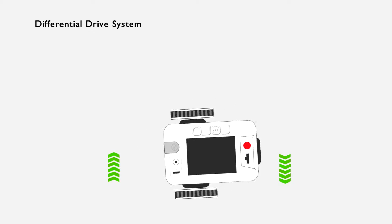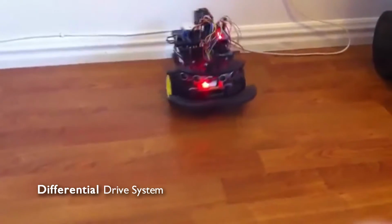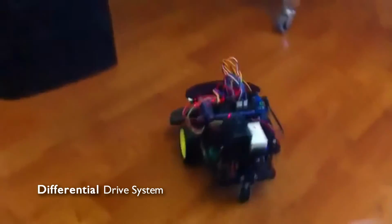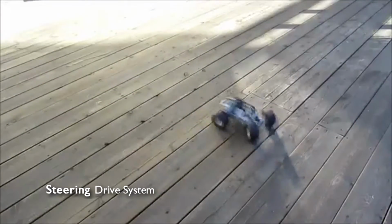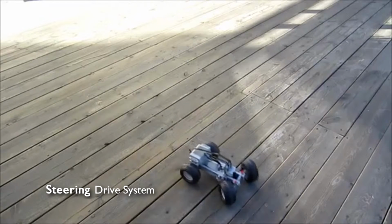at the same speed. Although differential drive system enables a robot to move around flexibly, it needs 2 powertrains or 2 motors to deliver torque to 2 independent drive wheels. It is impractical for vehicles on the road to have 2 engines due to the cost and complexity. Thus, actual automobiles use steering drive system where only 1 powertrain is needed.